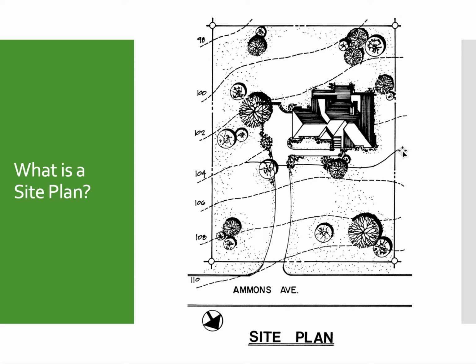So this area between the dash line and the solid line is currently sloping down, but we're going to grade it out. And so what will happen is this whole space between here and here will be the same elevation. I would have done a swale on each side just to make sure that the water does not, and I would have,